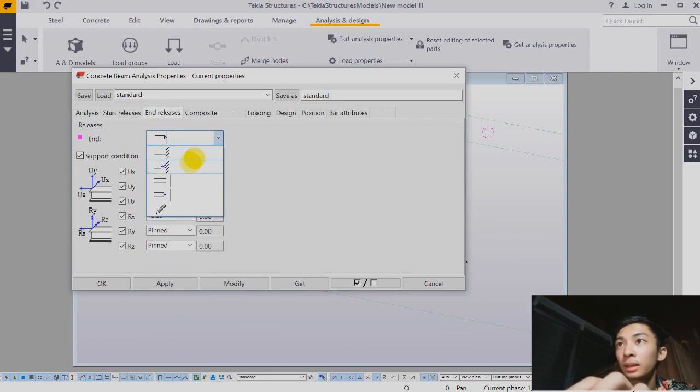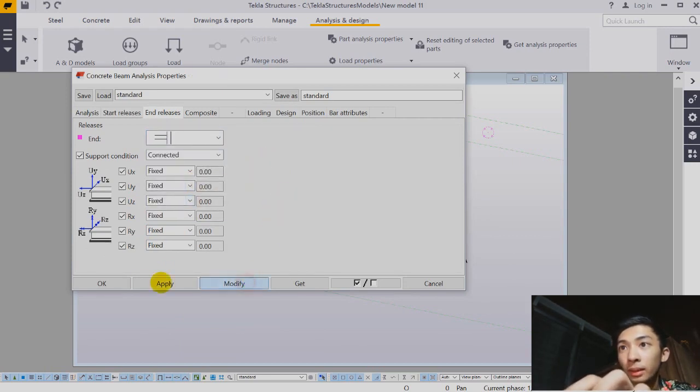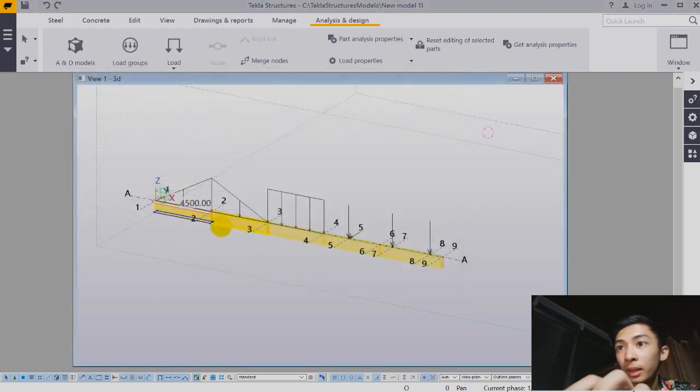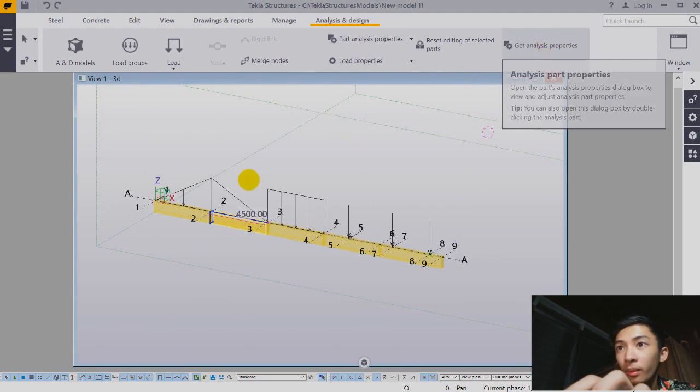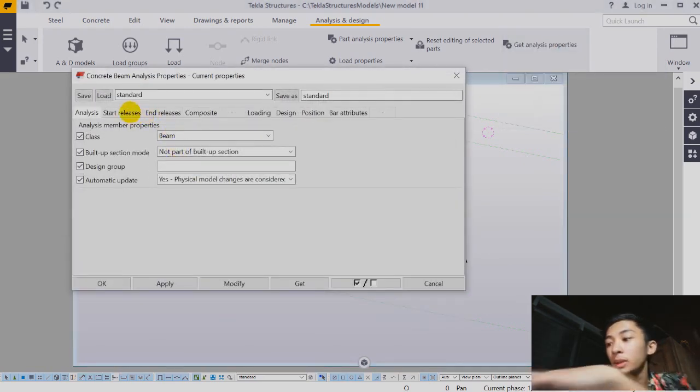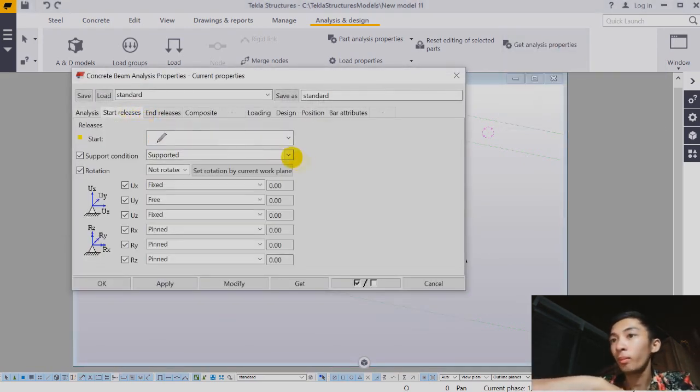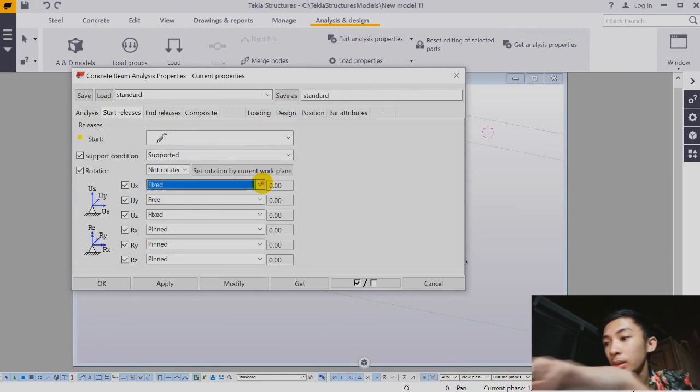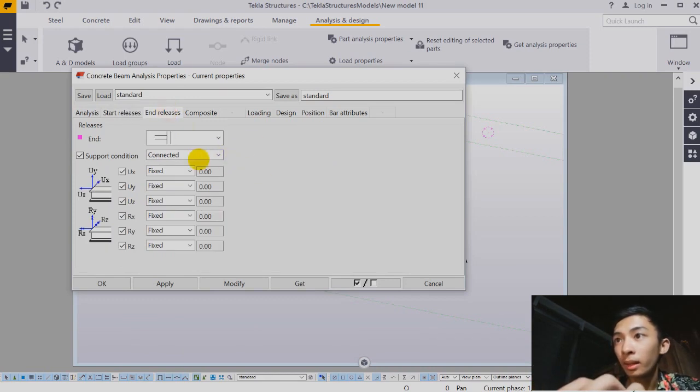Press escape. Then for the last load, double click on the load, then change the load form to linearly varying. Then change the value of P1z to 0. Change the value of P1x to 9,600.